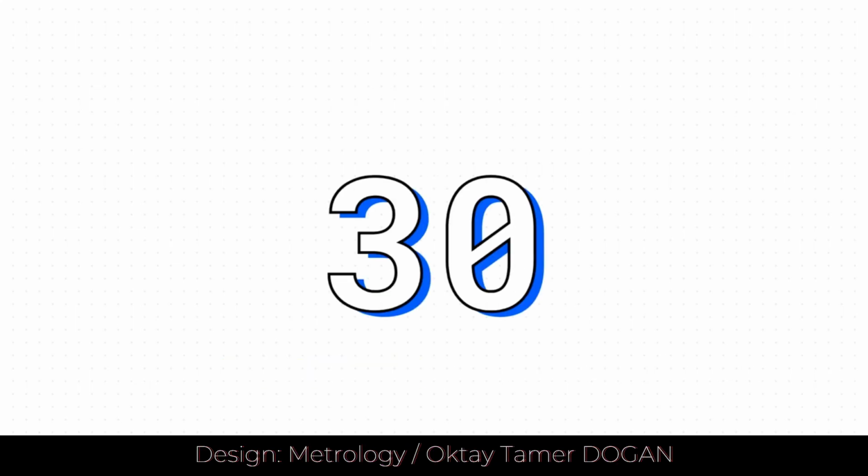Now, in calculating our next gremlin, temporal instability, you just have to remember this golden rule of 30. The guidelines state you can't just flip the chamber on and start measuring. No, you must wait at least 30 minutes after steady-state conditions are reached, meaning the temperature isn't systematically drifting up or down anymore. Once that initial 30-minute stabilization period is done, you must then record at least 30 measurement values over the next 30 minutes. This rigorous rule of 30 ensures that any short-term cycling from the chamber's heating or cooling compressors is fully captured and averaged out in your data.